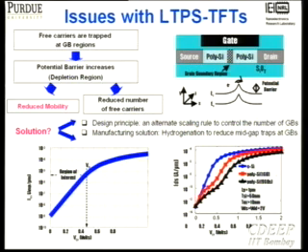But if I were to compare crystalline silicon with some of these polysilicon technologies having different grain boundaries, in this case the red one shows a grain having one grain boundary, I think it was a 200 nanometer device. And if I look at a polysilicon with 9 grain boundaries, what you see is the characteristics of these devices. If you do the right kind of optimization, you can get a reasonable device. It's not going to be the best of devices. You're not going to be trying to replace silicon with those devices. But the question is, can I really do what I want to do? In this case, doing online verification and test.